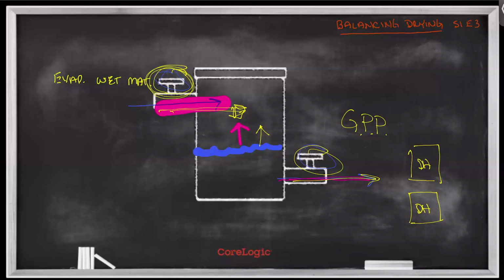Especially if you use the example dehumidifier calculations that are in the S500, those are gauged to handle the amount of evaporation that you should be expecting based on the size of the wet area that you've established, right? You measure out the area, you find out how much surface area we're dealing with. You assign a class of water to that. You run a calculation, cubic footage divided by a factor, et cetera. And that gives you an amount of dehumidification that should be adequate unless there are more wet materials